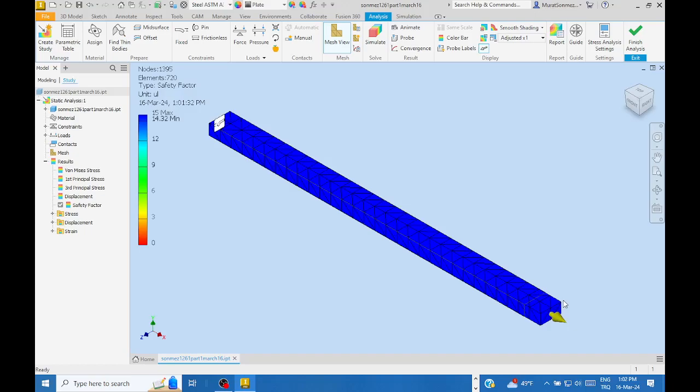It is going to be more quick response. So when we see that the factor of safety is too much, then obviously, if it were 1 or less than 1, we would say that yielding will occur. But it is greater than 1. So this means our threshold value, the yield limit, will not be exceeded. This is one method. Have a look at the factor of safety.